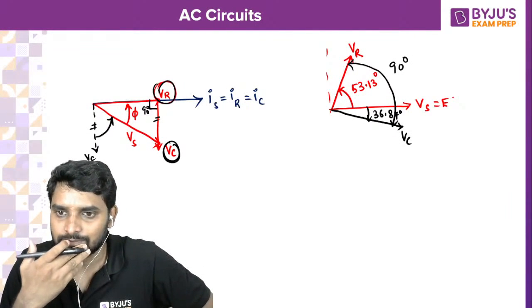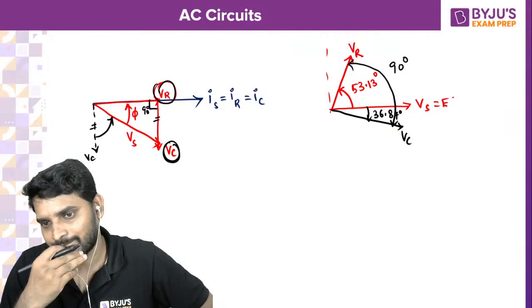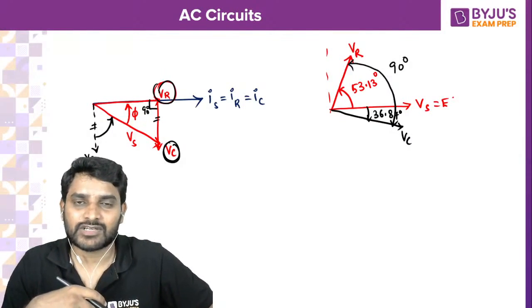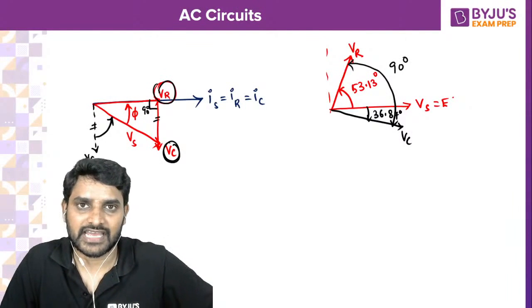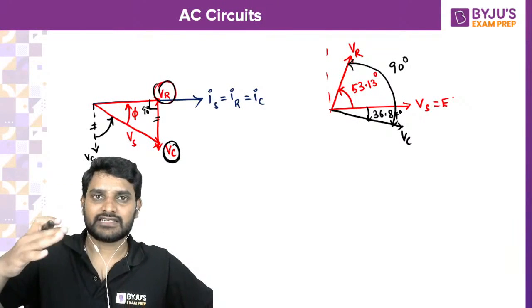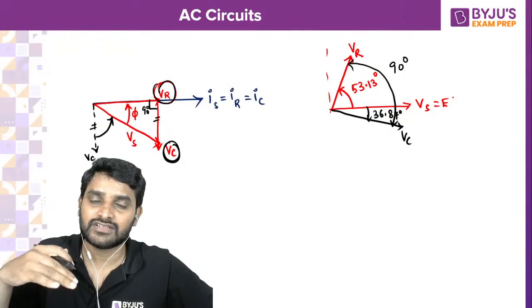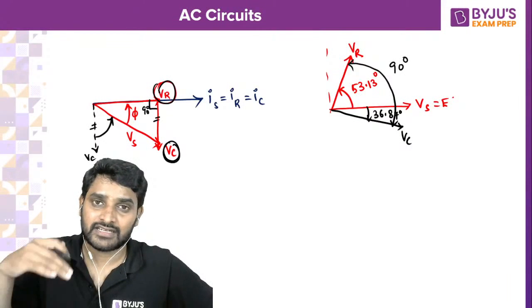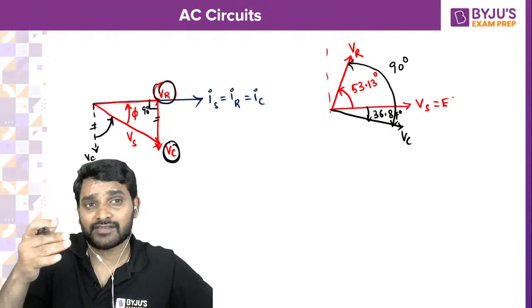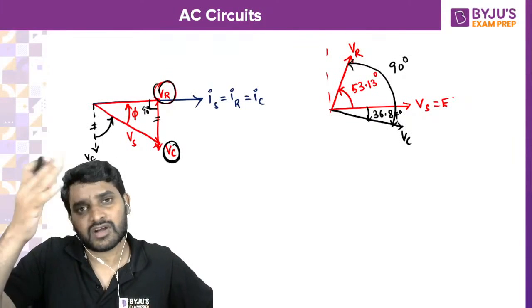Ananya Rai, what is your doubt? It is actually reactive power flow. The physical significance of leading and lagging is that it represents reactive power flow direction. Capacitor current is leading with respect to voltage. If you take an inductor and a capacitor, you get inductor current lagging and capacitor current leading. So the inductive reactive power component will be downward, and the capacitive reactive power component will be upward.